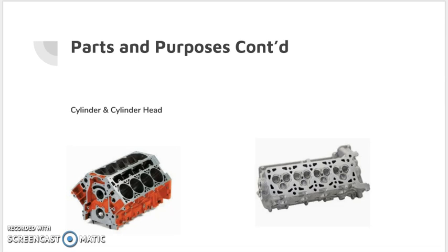At the upper end of the cylinder sits the cylinder head, which is the picture on the right, and at the bottom end the crankcase is bolted on. I'll talk about the crankcase later. The upper side of the cylinder is a combustion chamber where fuel burns. To handle all this pressure and temperature generated by combustion of the fuel, the cylinder material should have a high compressive strength, so it is normally made by high-grade cast iron. The main function of the cylinder head is to seal the cylinder block and to prevent any gases from entering and leaving.